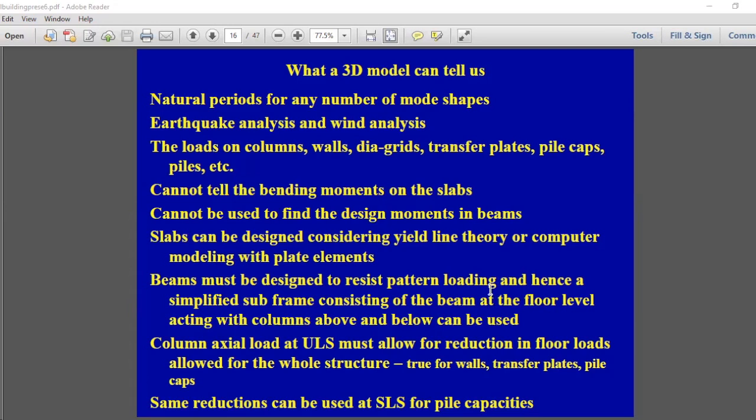The kind of live load reduction that we do for all the columns will be applicable for piles as well. Even for the foundation, we know that the full building cannot be loaded fully to the capacity of the live loads that we have considered, because all these live loads contain an allowance of about 50% to allow for dynamic effects. So the actual live load that comes on the structure may be only about 40 to 50% of the live load that you consider based on various guidelines.